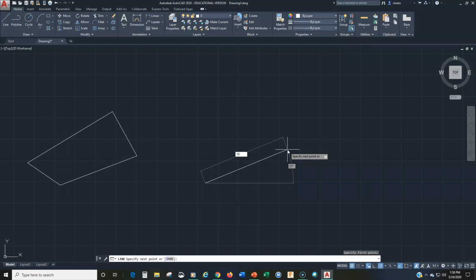Now here's the question, how do we jump? Notice that when I typed in, the blue box was around the distance, and that's where it goes when I type in 10. But how do you think I jump over to the 21 and change that to, let's say, 30 degrees? Well, we do that with the tab key. If I hit tab, now it jumps over there. Notice that the 10 has a lock symbol there, so that's locked in. So I can go 30.